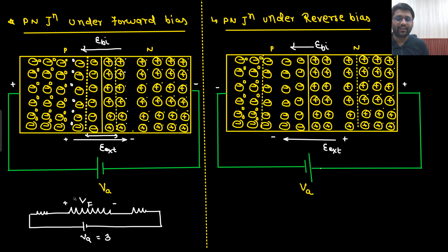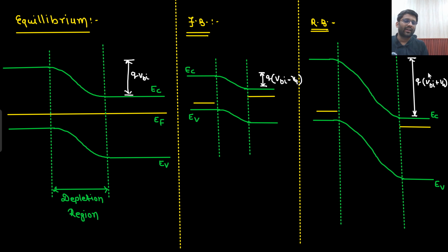And this point in great detail we have discussed when we studied PN junction under forward bias and reverse bias. But as of now, what you will understand is that, sir, whatever the potential that you have applied, complete potential is coming across the depletion region. That's why I have put V built-in plus VA, V built-in minus VA. The barrier has increased here.